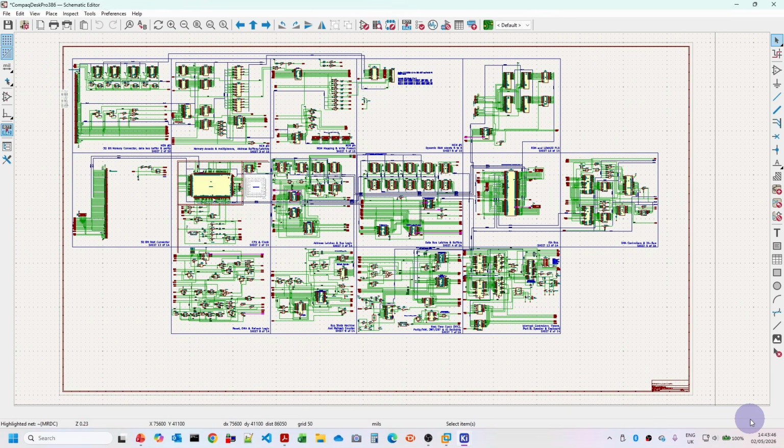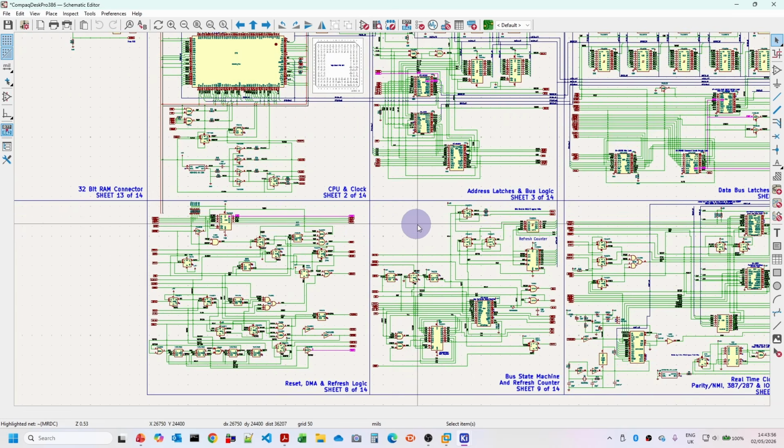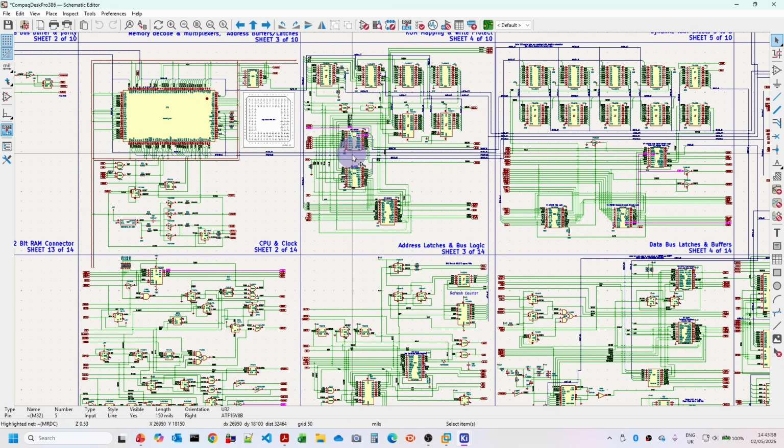So I'm going to leave the video there. In the next video, I'm going to be carrying on looking at the laying out of the buffers, latches and the control logic, getting the PLDs for the control logic, which is very much these ones here, here, here, here, here, and all these chips, getting all these worked out so we can lay them out around the processor. It is taking quite a while to get sorted, but hopefully within the next week or so I'll have the PLD rules for these old PAL ASM format files converted into more recent WinCUPL syntax.